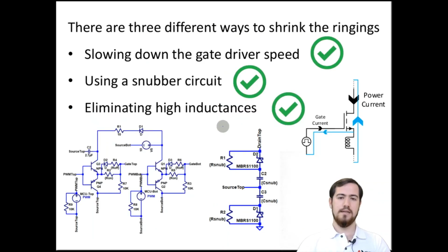So this is the last slide of our design. In these two courses, we investigated the design of a gate driver. We also checked a snubber design to eliminate the oscillations and to reduce the voltage stress. But the most impactful designs should have optimized layouts to eliminate any requirement of a snubber circuit or slowing down the gate driver speed.